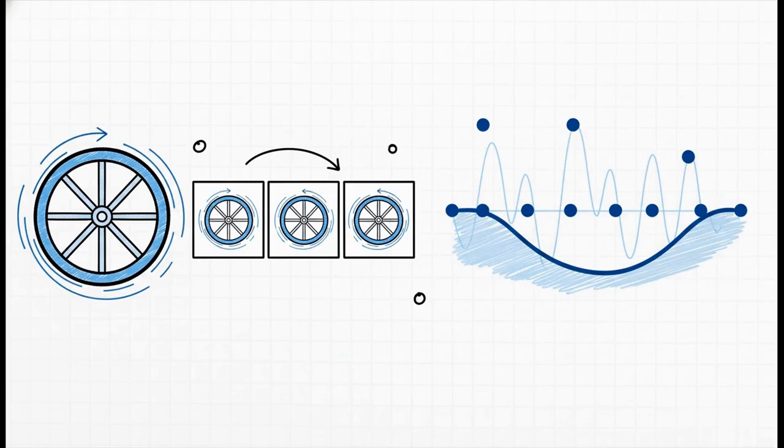The best way to think about it is like watching a car's wheels in a movie. You know how sometimes they look like they're spinning backwards? That's a visual alias. Same thing happens in electronics. If you have a signal at, say, 1,000 hertz, but you only sample it 800 times a second, your computer will mistakenly see a totally different, much slower frequency that doesn't actually exist. It literally invents a signal that isn't there.